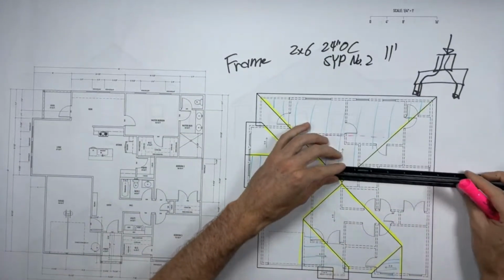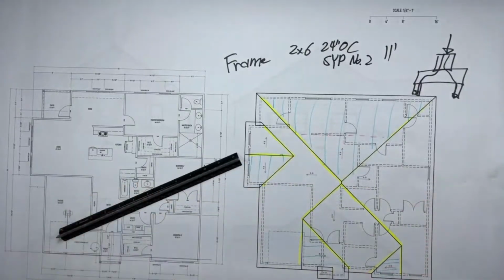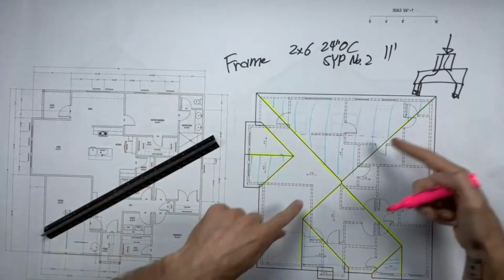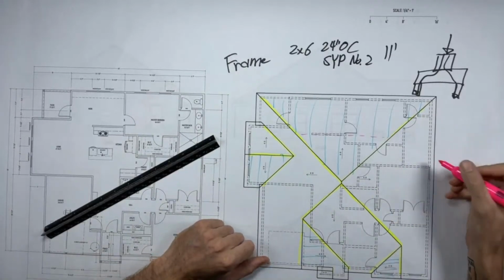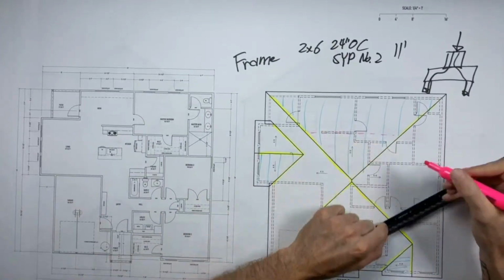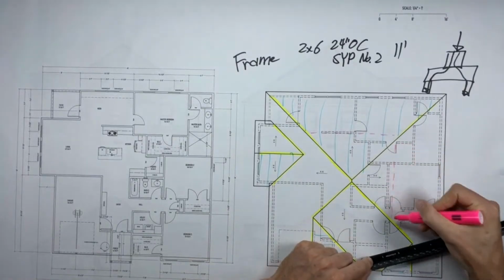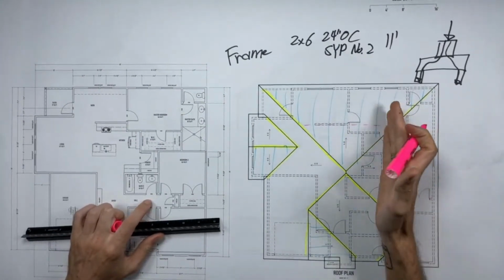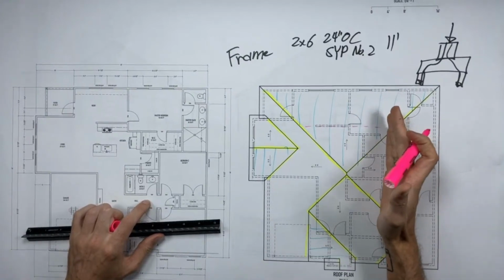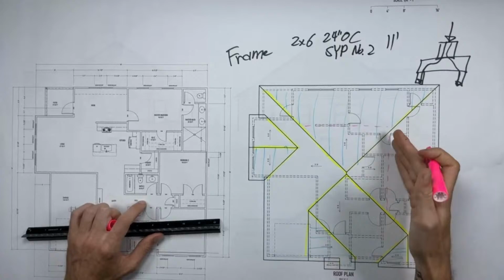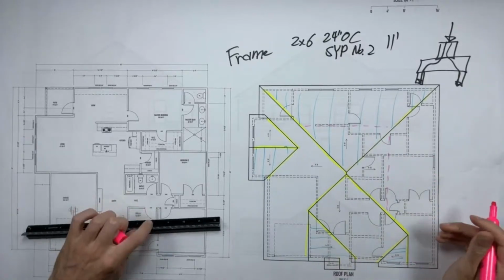I'll turn the scale this way. That is also 20 feet, which should make sense because that's almost no ridge, which means this building is almost completely square. So I'll do the same thing here. I'll go in about 11 feet to there. So that, I would call that a purlin line. That's going to be a member underneath all the rafters, connected to all the rafters with some braces. And that's going to support the weight of the rafters in that line.